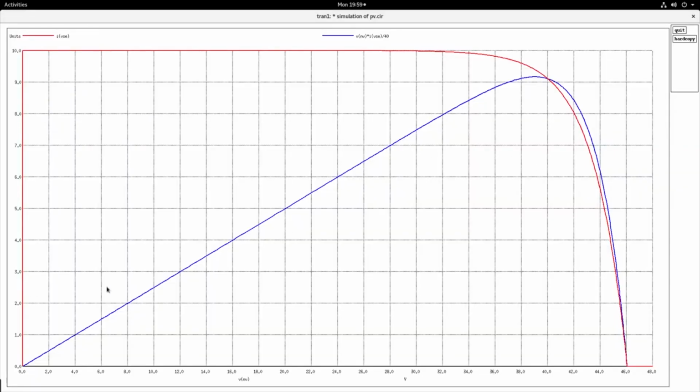You see it has plotted this, and as expected, short circuit current 10 and open circuit voltage around 46. And see, current doesn't go negative. Beyond that, current becomes 0 because we have set a clipper limit for the current going negative. So that is advantageous, and this blue line is the power curve. Of course, you can try for various combinations.